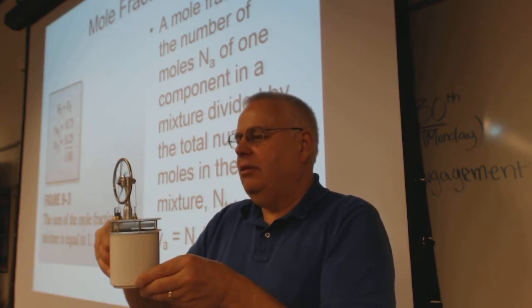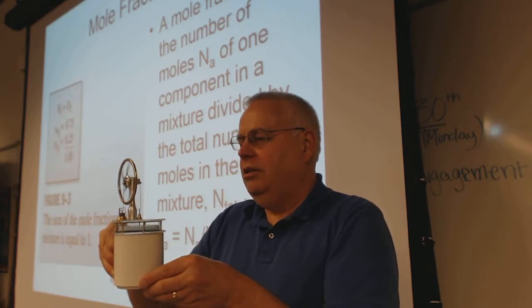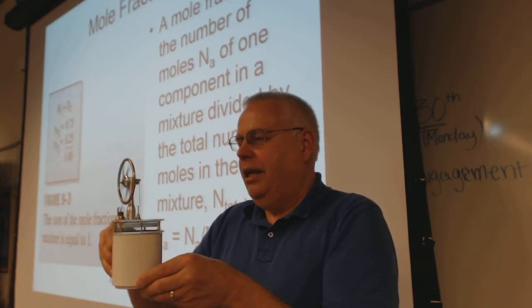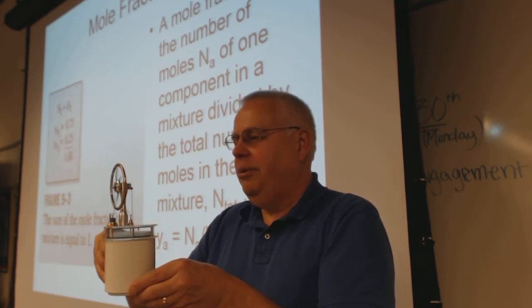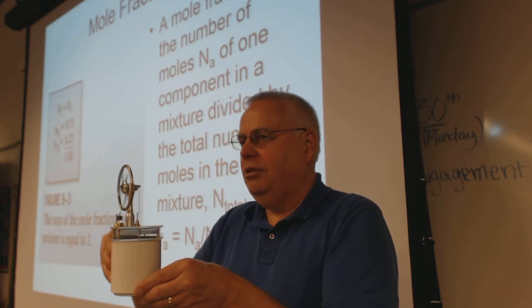And then when the little blue piston goes down, most of the air is exposed to the top surface, and the top surface is colder. It's room temperature. And the air wants to contract, and it pulls the power piston. So each stroke on the power piston is a power stroke. And the displacer piston is just moving the air from mostly hot to mostly cold, and that creates expansion or pressure in an enclosed space, and that's what's driving it.